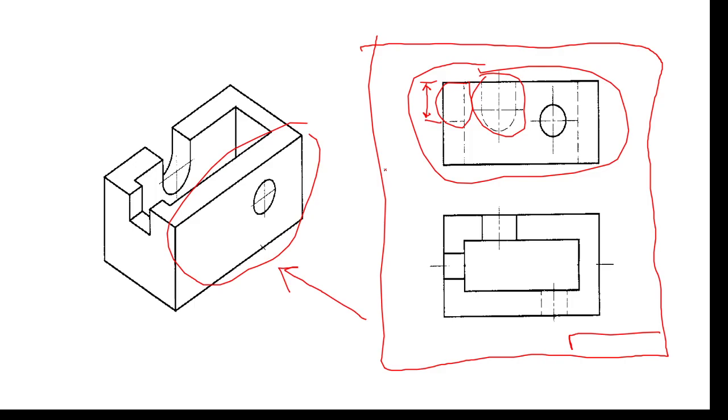What can we do? How can we get the right to show such a dimension? The answer is sectioning. It is an imaginary cutting process. One reason why a normal view is to be replaced with a sectional view is that we have some dimensions to show on the picture plane, but the entities are hidden. So, by applying the cutting process, we have the image of such features, for which the dimensions are to be shown on that picture plane, as if visible.